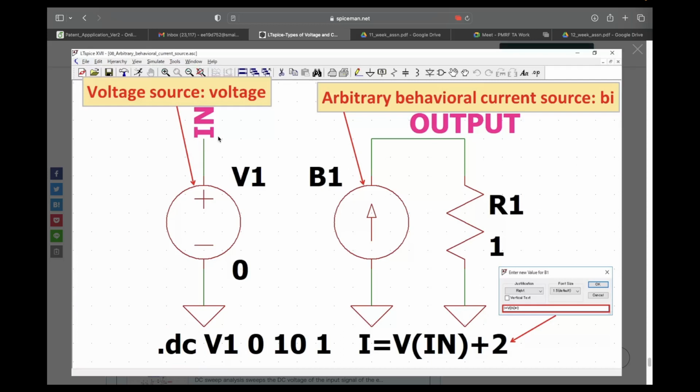We have to connect the current source in series with the resistor and the capacitor and voltage source, right? You have to connect it between the input and output. And what will be the current equation for this arbitrary element? I will be equal to G1 times difference of voltage between input and output, plus G2 times difference of this voltage square, plus G3 times difference of this voltage whole cube, and so on. Instead of putting it to ground, you will have to connect it to the input.